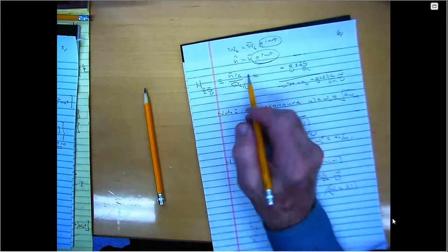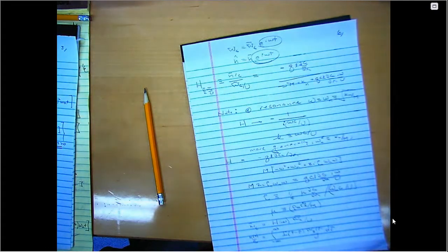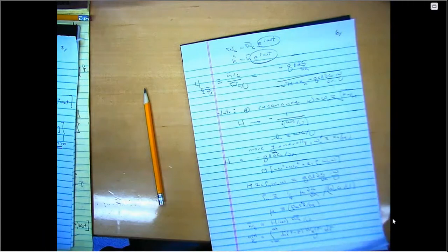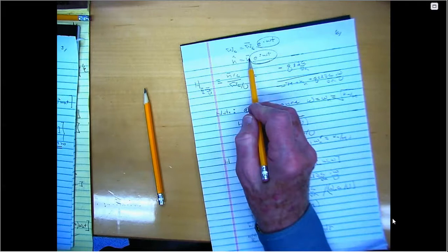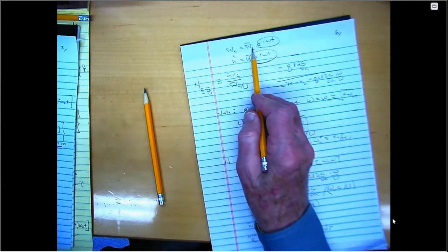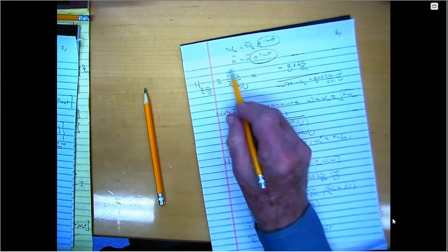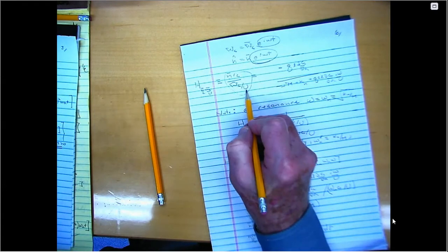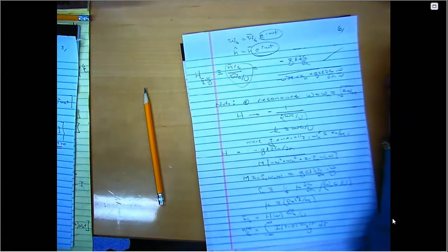Once I assume sinusoidal motion, that differential equation in time just becomes an algebraic equation, which depends on frequency because time has gone away. Therefore I can write the ratio of the amplitude of the response to the amplitude of the input: the amplitude of the bending of the wing to the amplitude of the gust. I non-dimensionalize it because I like non-dimensionalization. So I'm non-dimensionalizing h bar by c, and I'm non-dimensionalizing the gust amplitude by the free stream velocity. And when I do that, that's what I get. This is the transfer function.